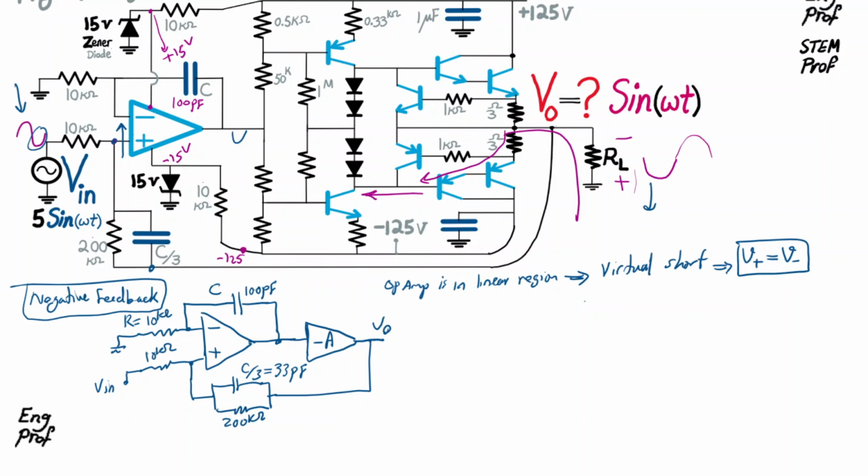Let's refer to that voltage. This is helpful. Let's refer to this voltage as voltage V. So it is equal to V. Okay, so just bear in mind that if this node is V out, this node is obviously V out divided by A with a minus sign, naturally. Okay, but it's obviously a relationship between negative V out over A and V, because it is an ideal op-amp.